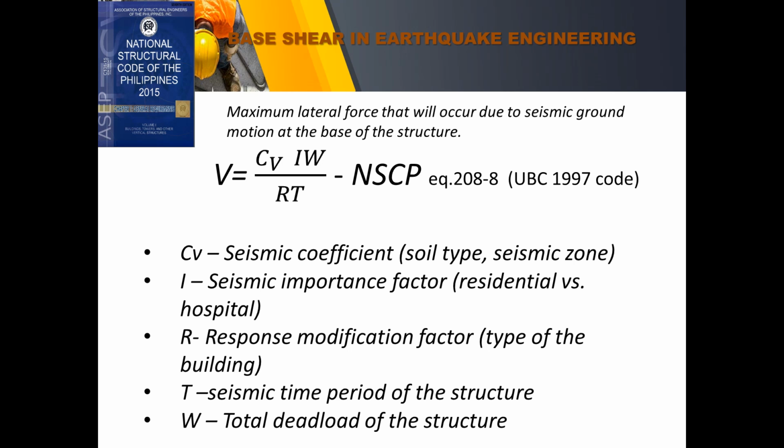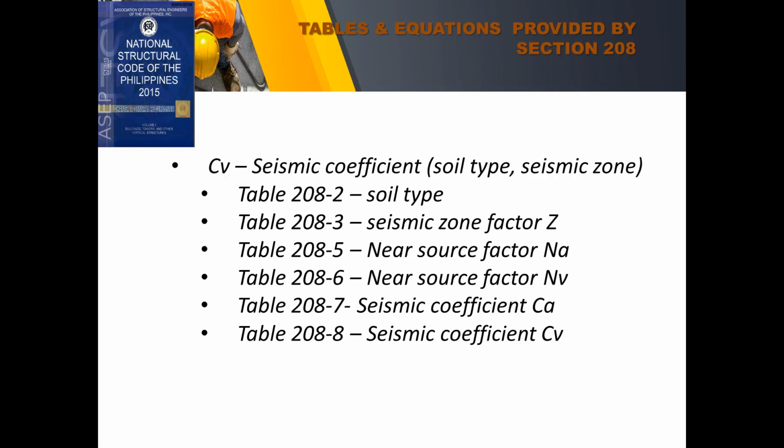T is the seismic time period of the structure, and W is the total dead load of the structure. And I think this will be performed in a separate subject called earthquake engineering. So for our consumption, just be aware that NSCP also provides those mentioned seismic coefficients. We have the soil type, seismic zone factor, near source factor, seismic coefficient CA, seismic coefficient CV.